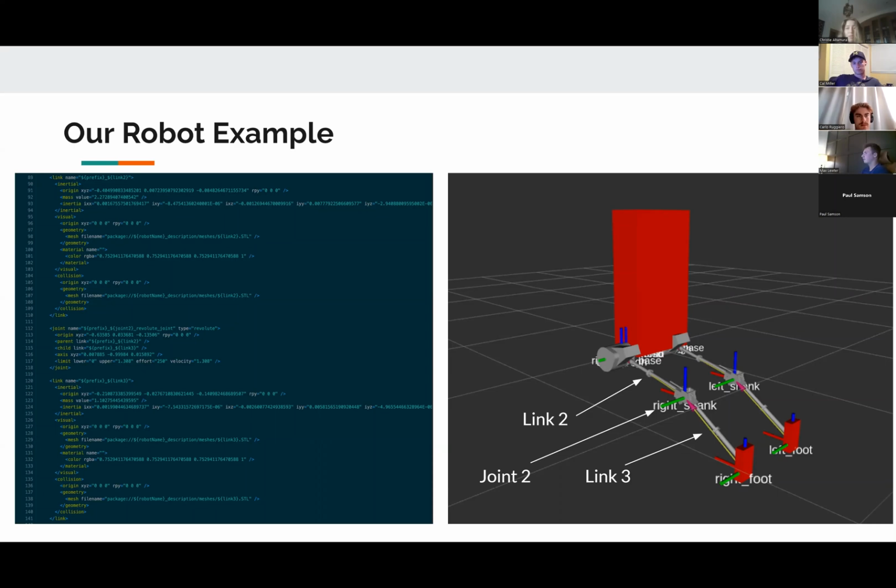Okay, so you're able to add inertia into Gazebo? Yeah, we're able to add inertia into the URDF. That's what you see there on the left. If you look beneath link 2, you can see there's an inertial tag with inertia in it. Like I said, a URDF is something within ROS.